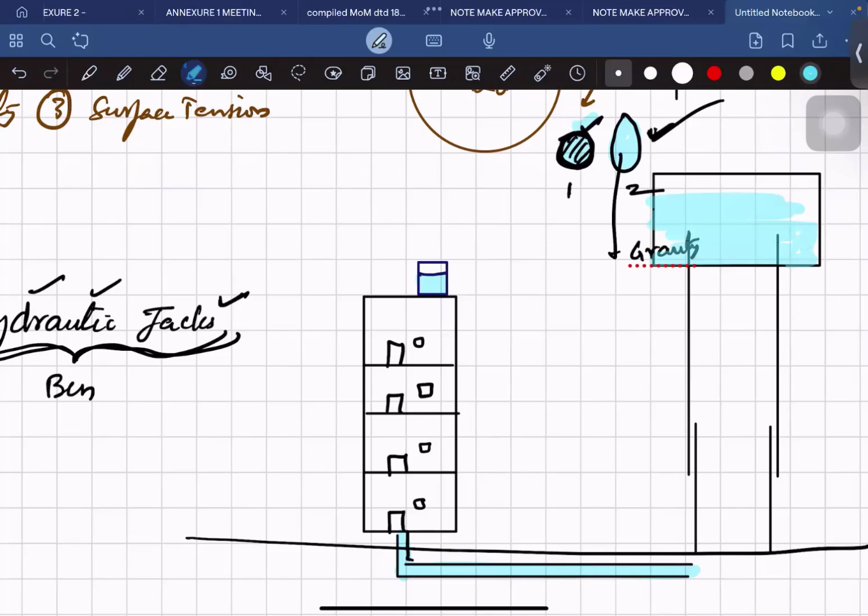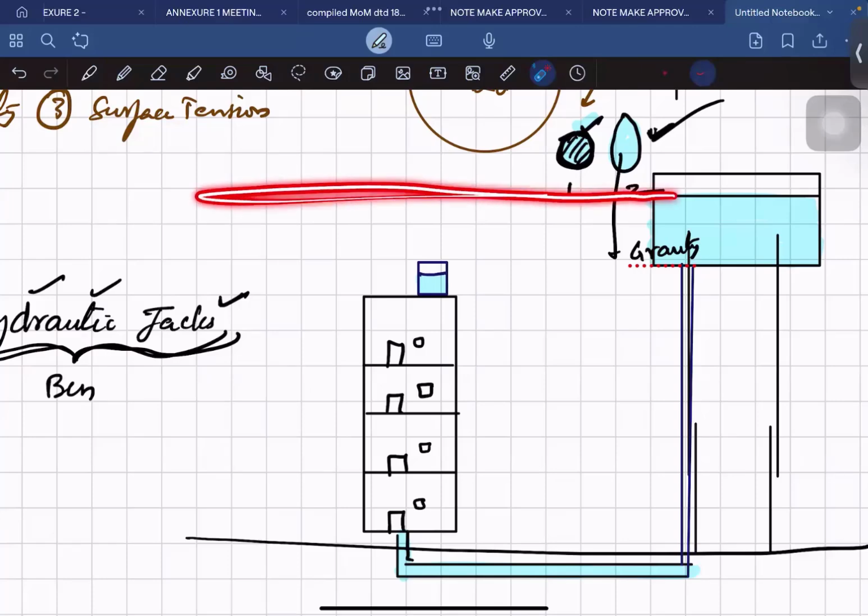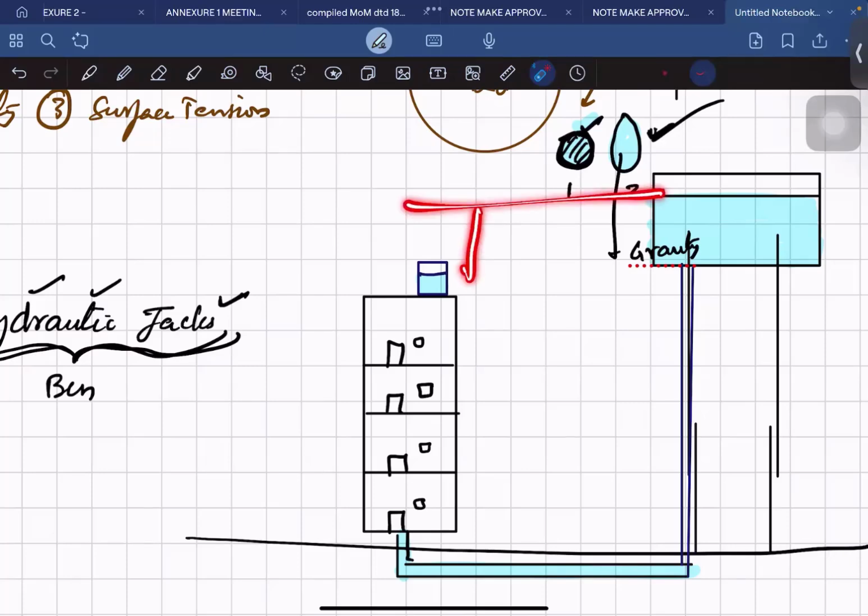Yes, individual areas have their own tanks, due to head difference. Yes, you are into the subject. You are right. There are two possibilities. One possibility is they construct the tanks so that the level of the top layer of the tank is above the level of that community, so that because of head difference, there will be flow of water in this pipe.